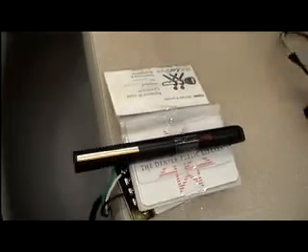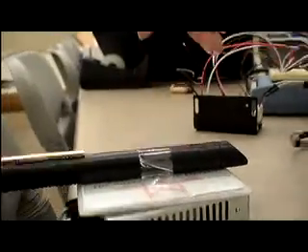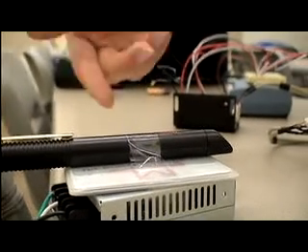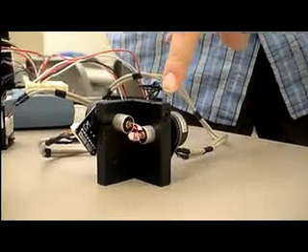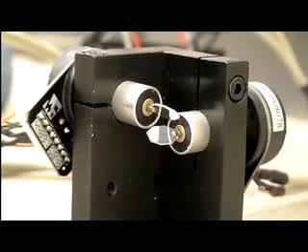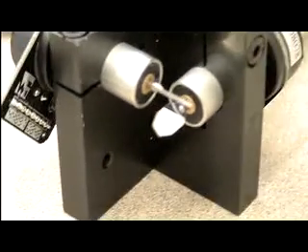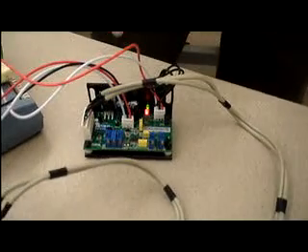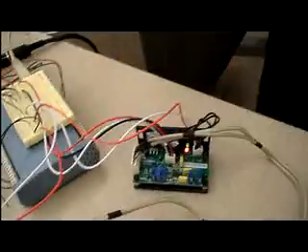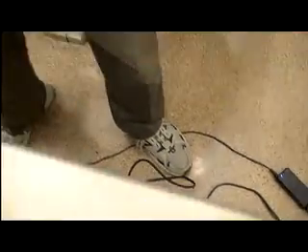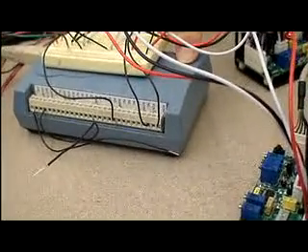Here we have just a basic laser pointer that's taped down onto this thing to prop it up so it's at the right position. That shines onto this, a galvanometer system. These two things each have rotating mirrors that are controlled by these two galvanometer control boards, which are each powered by a 15-volt power supply and receive a control signal from this DAC card, which is a Measurement Computing USB 3101 DAC card.